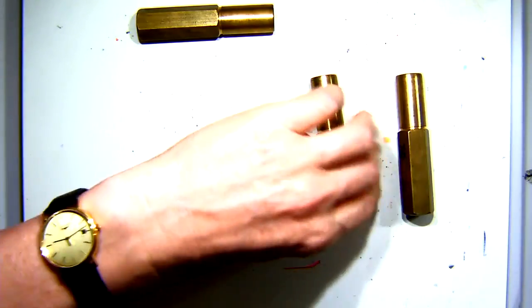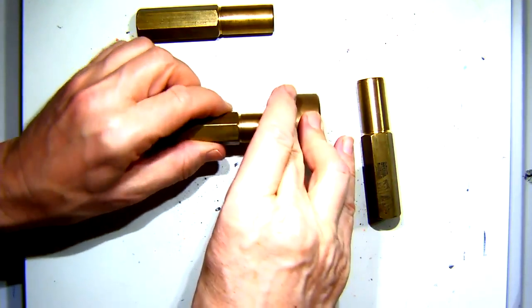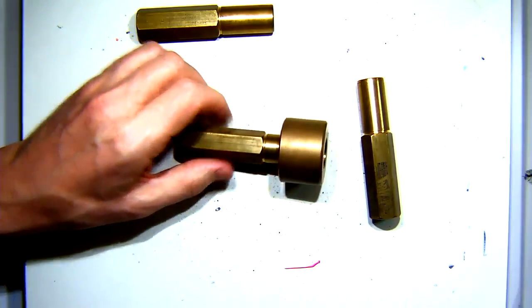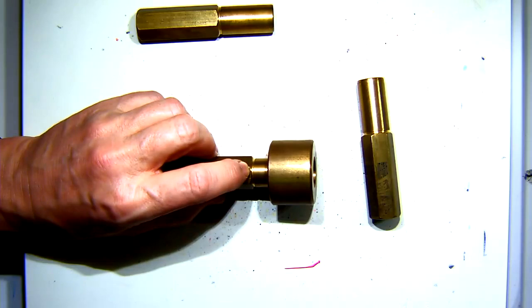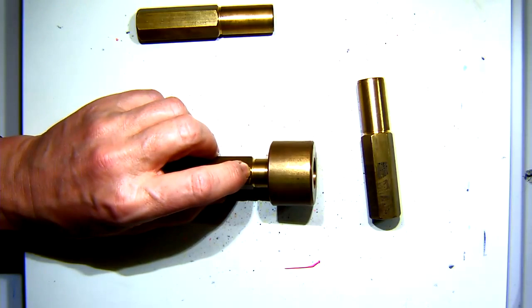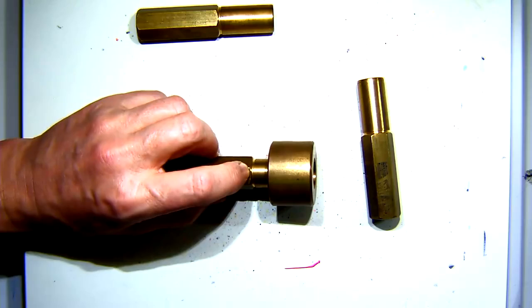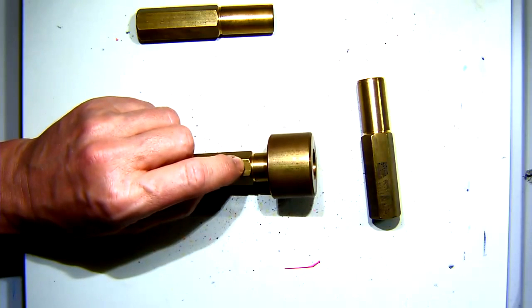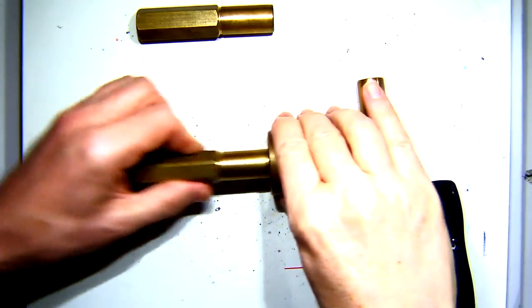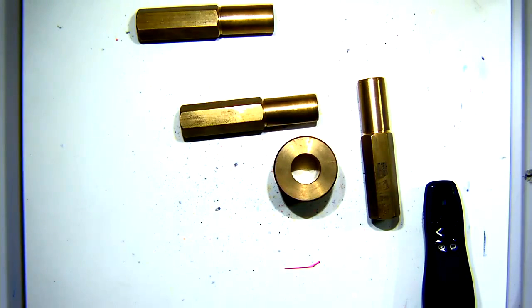For the transition, which is this one, now this one fits in just, which implies that the actual diameter of the shaft I'm playing with is somewhere there. If it was bigger within the tolerance range available, let's say that's 9.9 to 10.2, if I couldn't fit this particular shaft in, well then we're closer to the 10.2 than the 9.9. That's the literal diameter for that particular shaft. But the thousands and thousands that might be produced all have to lie within that range.